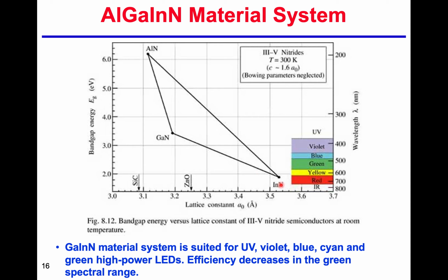And the other thing is indium nitride. Actually, it is easy to have what we call indium aggregation. So indium is kind of a metal. So if the metal aggregates, that will absorb the light. Which means for the gallium nitride system, when you increase the wavelengths, the efficiency drops a lot. So that is an issue.